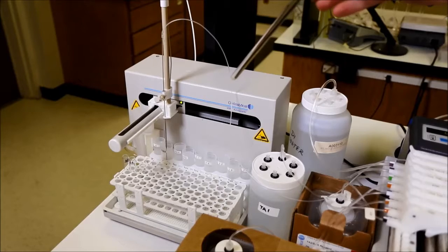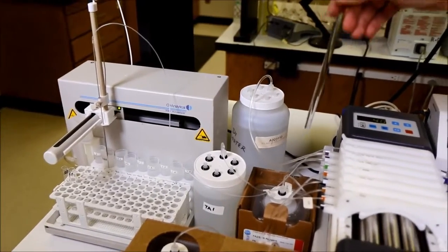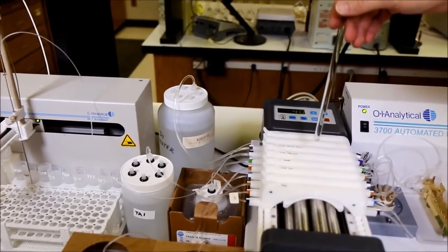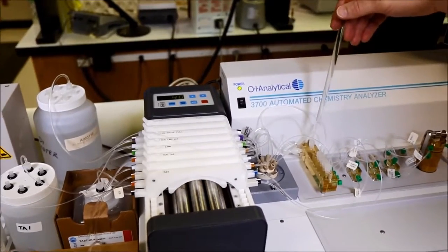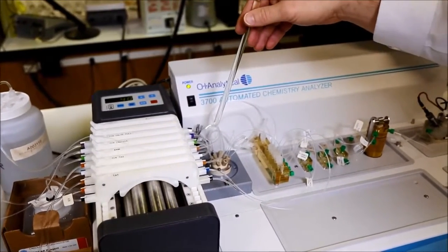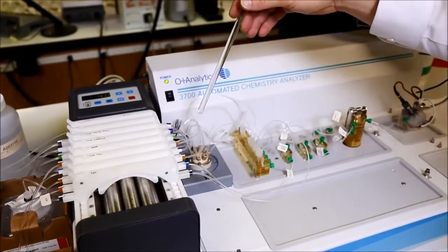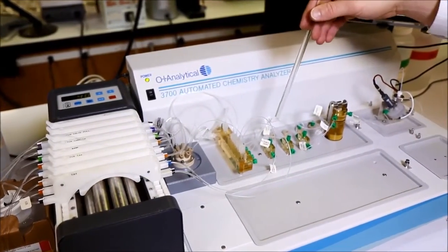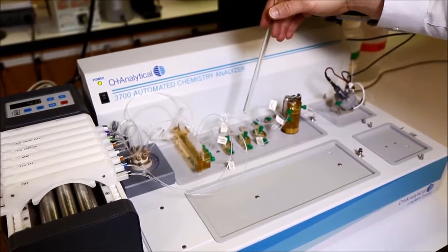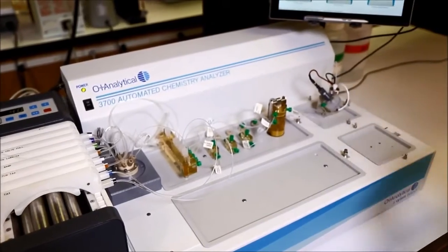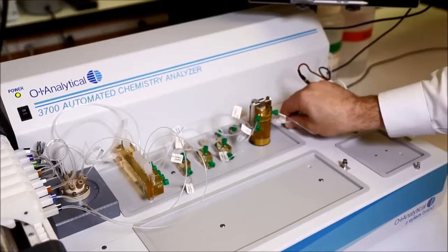Samples are introduced utilizing an autosampler and, along with the reagents, passed across a peristaltic pump and over to the distribution manifold. The sample fills the injection loop, and when the FIA valve actuates, sample is combined with TA1, air segmented, and then sent down to the UV digestion coil located on the lower side of the analytical cartridge.